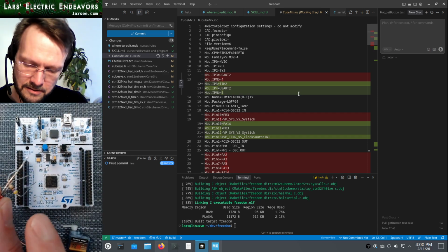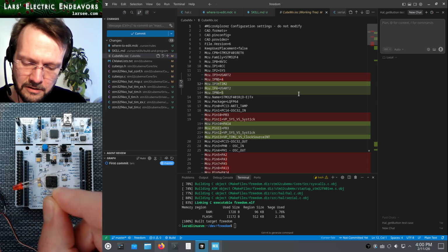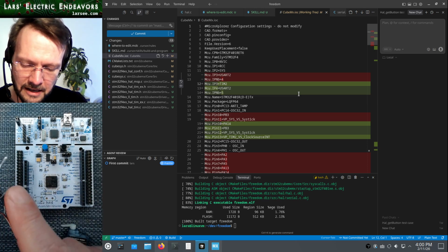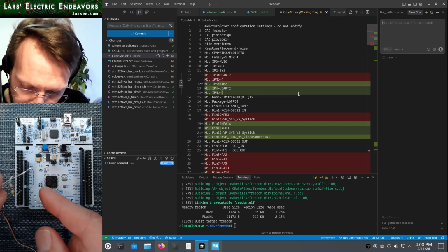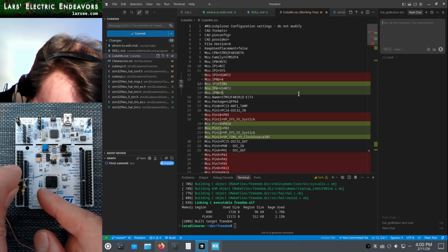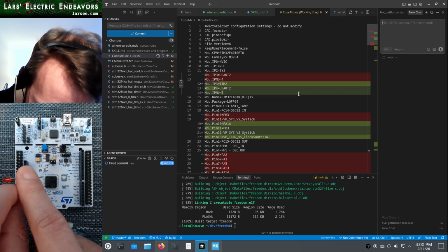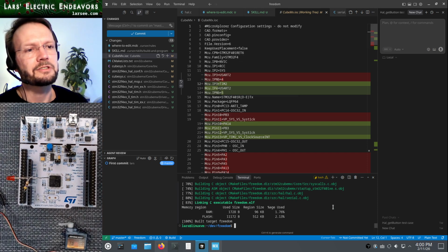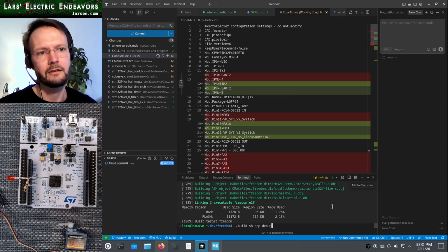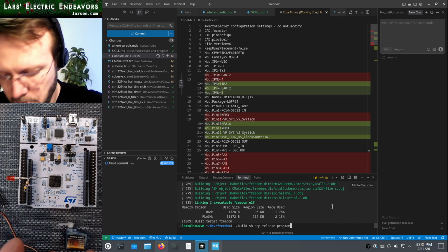The way I wired this is that the resistor end, this is a 470 ohm resistor on a red LED, has to go to positive, and the other end goes to negative, the way I wired it. So there, that should be correct. If we just try and run it now here, nothing is going to work, it won't make any difference. Also need to insert this.